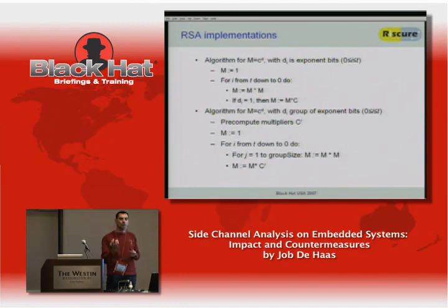So the multiplier is now dependent on the key bit, but the multiplies and the squares are equal for each 2 bits. So it's a simple way to do this, and it makes it at least resistant to the SPA attack. But this does not make it resistant to a DPA attack, because the constant that's used in the multiplier is still different for the key bits, and you can find that using a DPA attack.